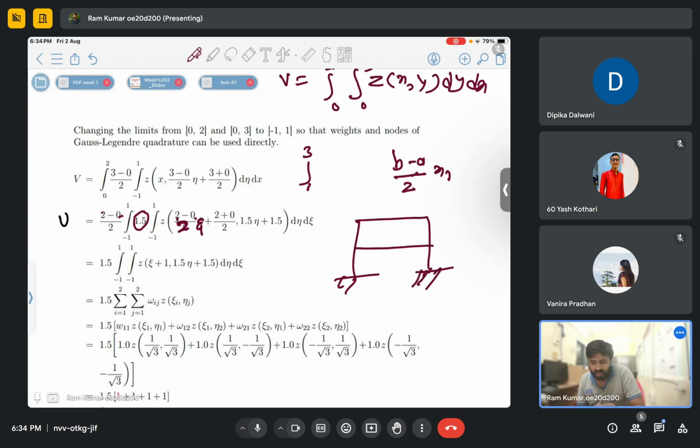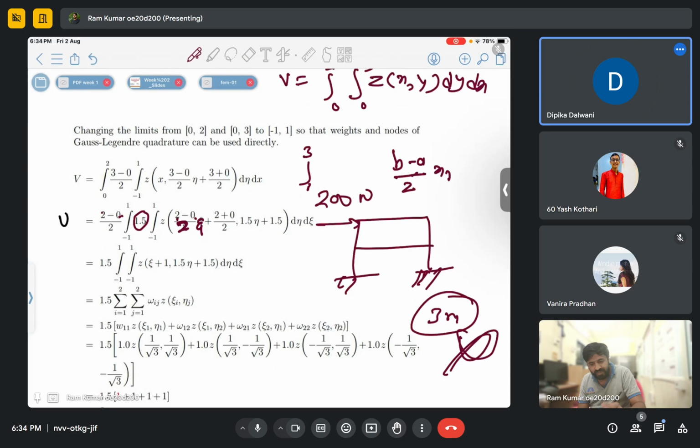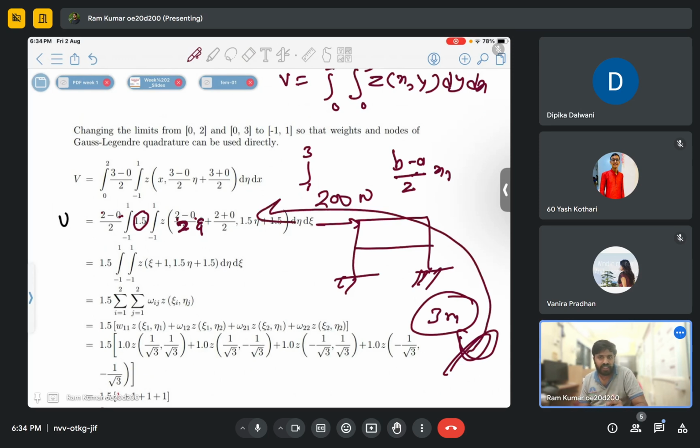Okay, I think. So, I'm putting some load at 20 Newton or 200 Newton, and you are getting 3 meter displacement, just for example. But you wrote your code, well, then we can think code cannot give wrong answer. But by our simple understanding, basic understanding, we can say this is totally wrong. It cannot happen. So again, we have to go and check how I wrote code. Maybe I missed some variable somewhere.